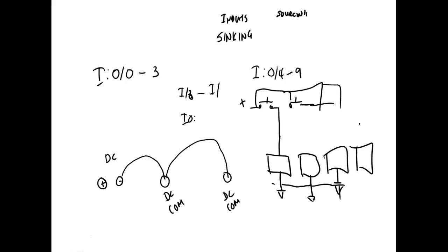Y'all understand that? Because we can program PLCs all day long. But if you don't understand how to hook these things up, you're not going to be any good to anybody. Right? You understand that? Well, if I use negative DC on this guy and I have negative over here, I could sit there and hit that button all day long and nothing's going to work. It's not going to happen.